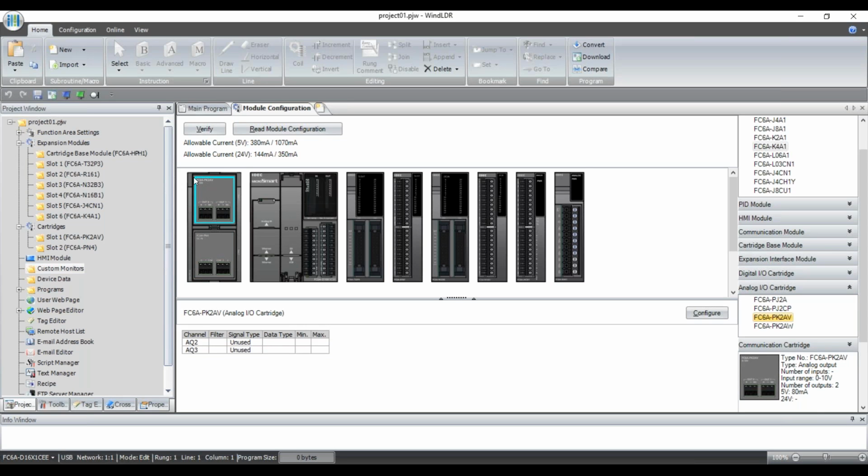All right. So the digital I/O cartridges, if you remember, we said it didn't matter if it was an input cartridge or an output cartridge, based on the slot position. Slot 1 used 630 through 633 for digital. Slot 2, this bottom cartridge slot, used 634 through 637. This happens to be an input cartridge. You can see I634, I635, so on.